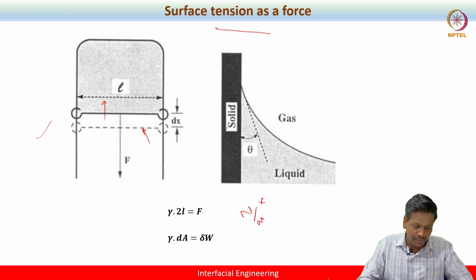So you can simply multiply this with respect to the perimeter. Here in this case, the perimeter is simply nothing but 2L, right? So when you multiply that with the perimeter, one would get force, which will be simply Newton. So you can also consider surface tension sometimes. You can also express surface tension as surface energy, which is nothing but joule per meter square. Okay, you can also express surface tension as Newton per meter, or surface energy as joule per meter square.